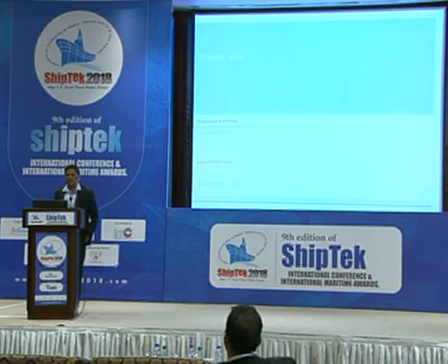I think the purpose is that it will not basically be 5 years. There is the class society, and then there is the flag requirement. As far as class is concerned, we are very clear that based on sensor data and condition-based monitoring, we will take the decision to postpone. Actually, it is already happening on a case-to-case basis, like 5 years becoming 6 years. But there is a flag requirement for bottom survey and so on. Once the technology is developed, I think the flag will be lenient to accept. That is what we assume.